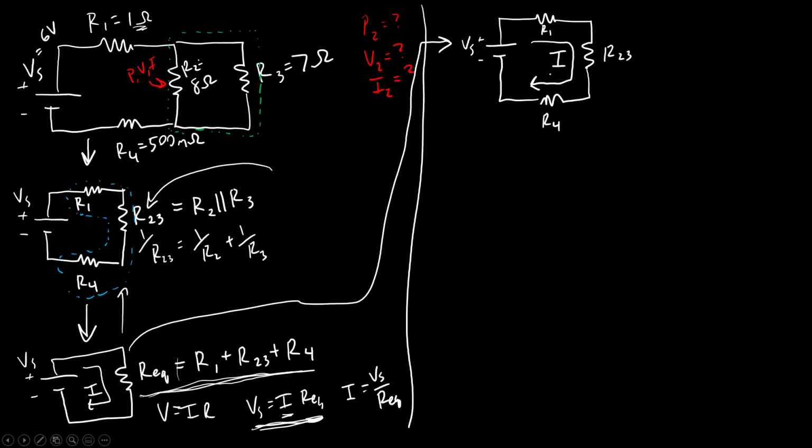And again, according to Ohm's law, if I know the current through a resistor, I know the voltage drop across that resistor. So I'm going to make up some intermediate variables here. I'm going to pick these 2 nodes and say I'm going to call this one VA, and I'm going to call this one VB for the voltages at those nodes referenced to ground. I haven't explicitly drawn the ground symbol in this circuit. Again, we have another video about that, but since we just have a single battery, it's implied that the negative terminal of the battery is 0 volts or ground. So I am going to make up, again, 2 more variables for these intermediate nodes between the resistors so I can solve for the voltages there.